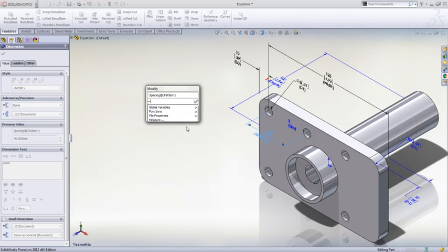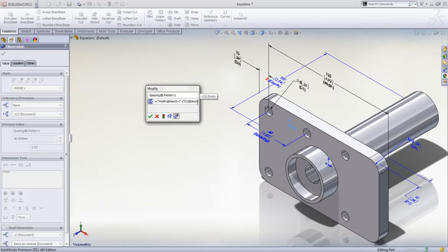By typing in the equal sign, SolidWorks starts building the equation and even colors our equation to let us know if the syntax is correct. In this case, we want to build an equation that solves the overall length and determines the hole spacing of these holes on the top of our part here. Making sure that we have our equation right can be verified by clicking the checkbox, and we get what our value should equate to. Clicking Rebuild will affirm that we've got the equation correct.